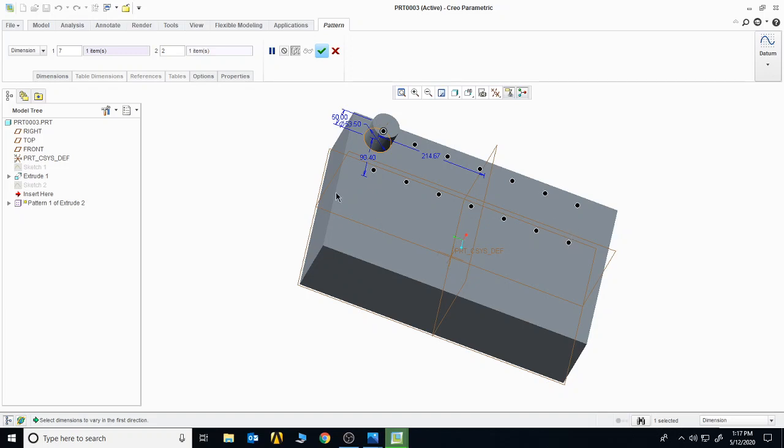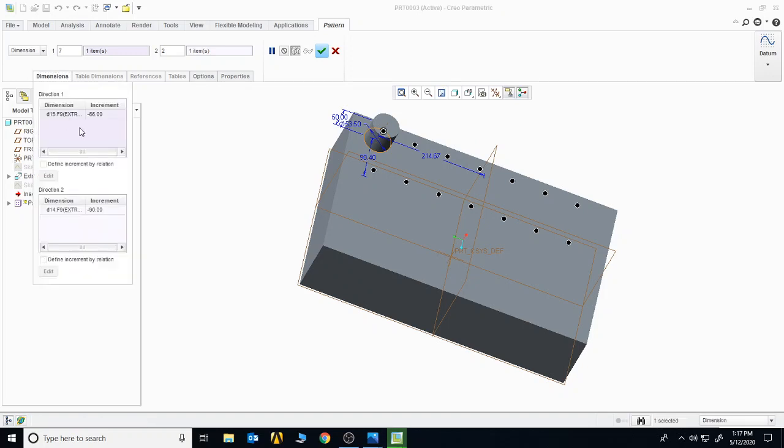You can also use the pattern command to either increase the heights or the diameters in incremental or decremental order. As the height of this cylinder is 50, and I want the height of this cylinder to be slightly larger than the previous, and so on in incremental order. So for that, I will go into the dimensions, right click here, click on the